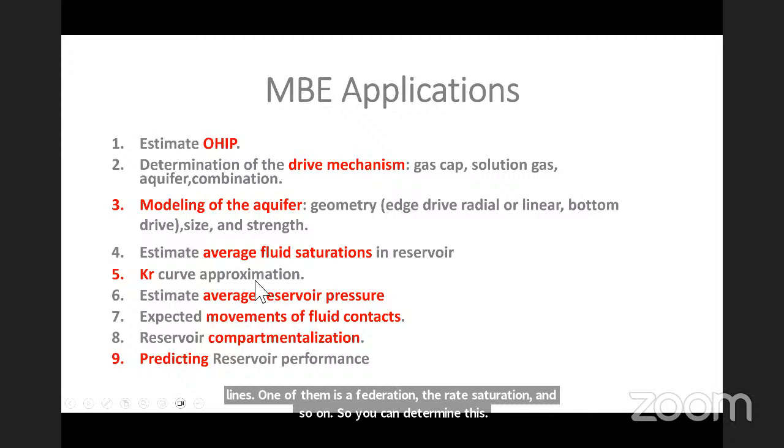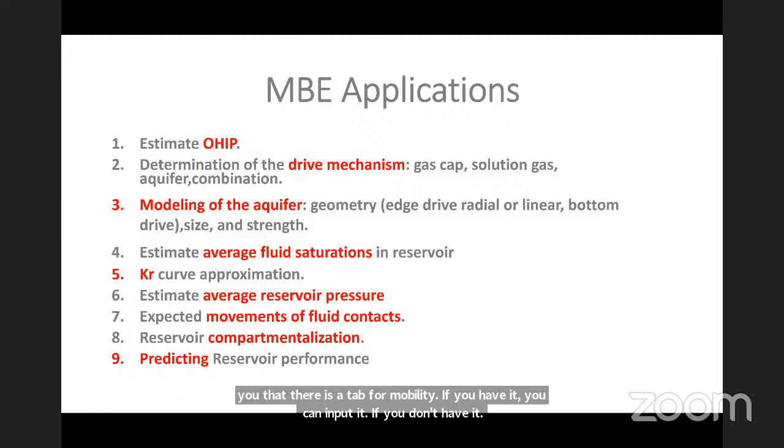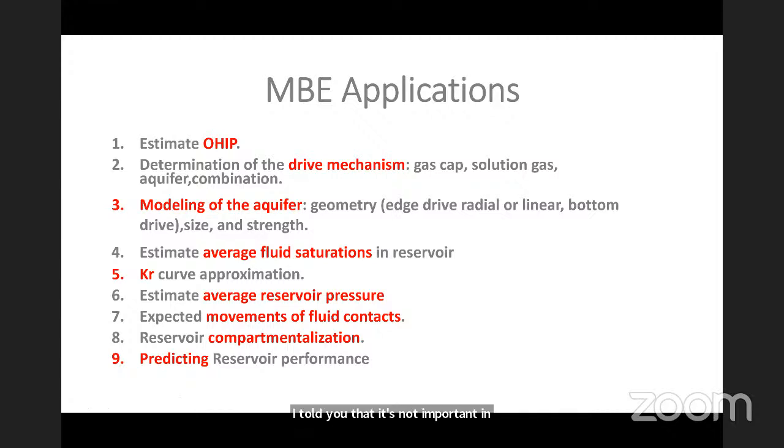The relative permeability as well. I showed you that there is a tab for relative permeability. If you have it, you can input it. If you don't have it, I told you that it's not important in the history and simulation. It's important for the prediction.